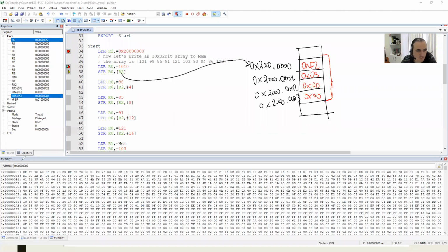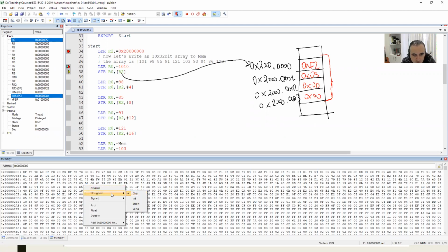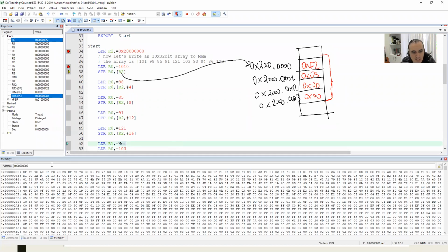Well, actually, you have this memory here, guys. By selecting commands, call stacks, memory, you can click the memory and see a part of the memory. I'm going to be seeing the memory location starting with 20 million. So guys, in this notation, since I'm using unsigned char, it shows hexadecimal 8-bit values for each location, which means, guys, this is 20 million.